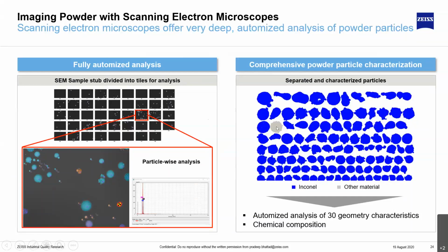So that's the level of information you can start getting very quickly right at the powder, even before the powder goes into a build. So you can think about aluminum powder coming into an Inconel build. Now you pretty much vaporize this material. If the vapors are not able to escape, that becomes trapped porosity in your part, or that can create instability in your melt pool that can have its own different effect.